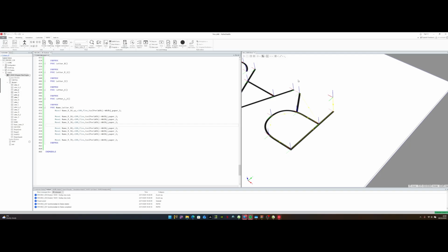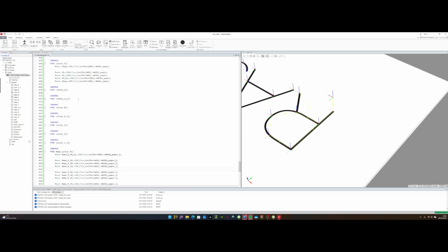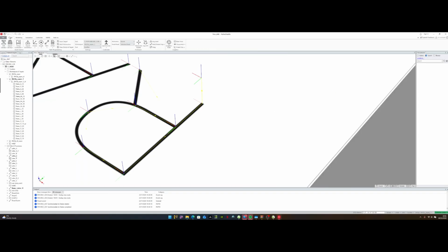Okay, so this is how you're going to be modifying your code to get the robot to jog precisely where you want it to go to. I'm going to show you how to quickly do a move C without having to write out the logic yourself. You can decide that you want to write the logic yourself, and you do your move C, you put the two targets that it's going to move C through. That's fine, but I'm just going to show you a shortcut on how you can do it.